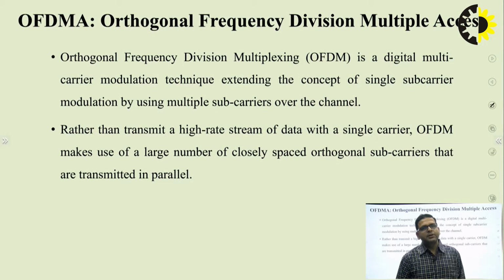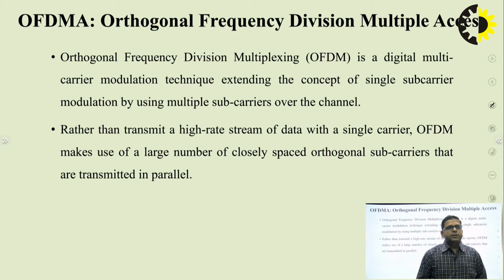So, multiple access techniques are designed to share the communication channel among different users so that it can be utilized efficiently. In the frequency division multiple access technique, we have seen that the entire frequency range is divided into narrow frequency bands, and each band is allocated to a dedicated user.